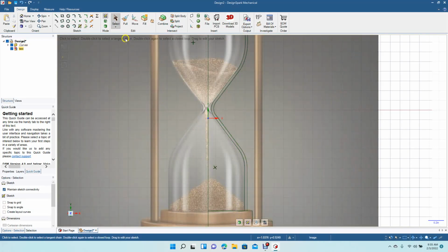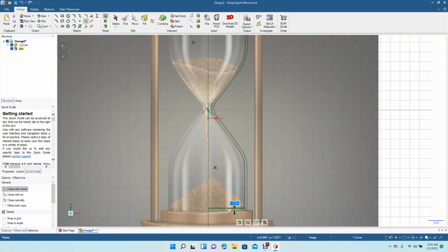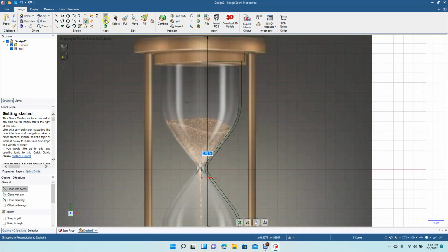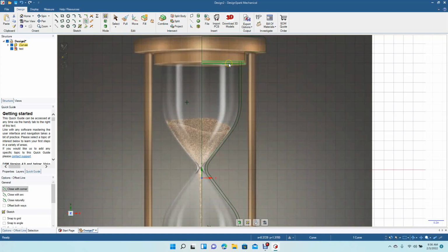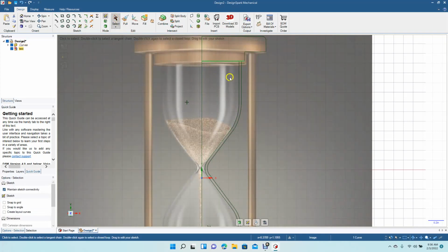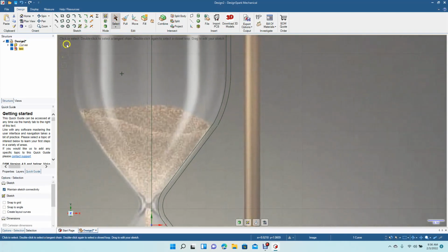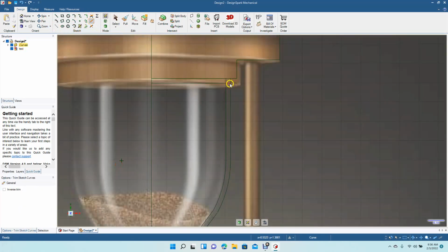Now we got to do the offset on the bottom and the top. So we'll grab the offset. Let's click up. 0.03. Okay, let's pan down. Let's get our offset. Oops, I keep clicking on stuff. Let's grab our offset. Click that. Go down 0.03, enter. Okay, now we're going to start trimming this stuff. Let's Control plus to zoom in. Let's grab our pan tool. Let's pan down. Go ahead and grab our trim away.